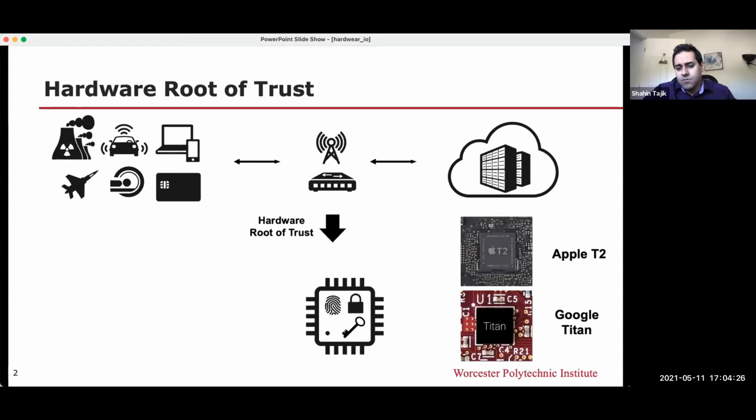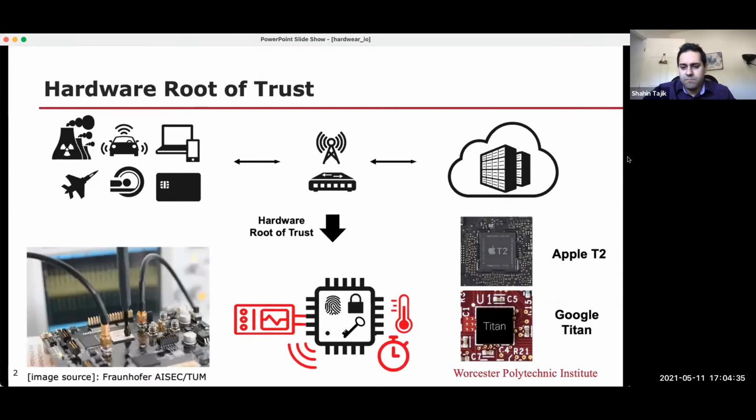But as you all know, in this community, pushing everything to the hardware doesn't necessarily make everything secure. We have known for probably more than 2 decades now that computation on a chip is a physical phenomenon, which means that when you are doing some computation on a secret or on some assets, the information leaks through unintended side channels. Examples are power consumption, temperature, timing, and electromagnetic radiation from the chip. These are probably the most popular side channel techniques that researchers are investigating.